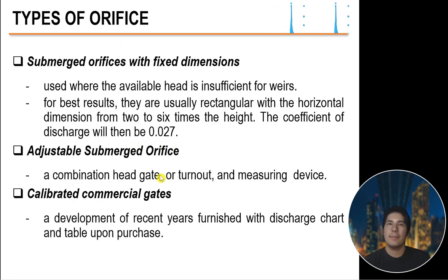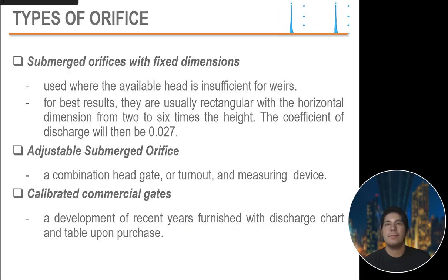We have also the adjustable submerged orifice. This is a combination of head gate or turnout and measuring device. We have also calibrated commercial gates. These are developments of recent years, furnished with a design chart and table upon purchase. Parang may standard na siya from the manufacturer.